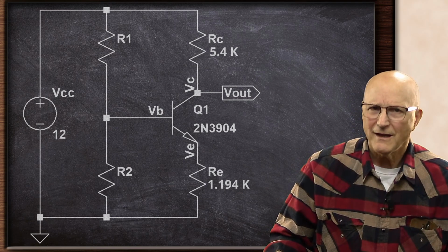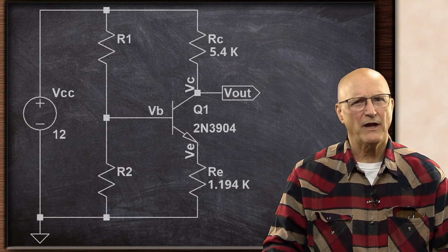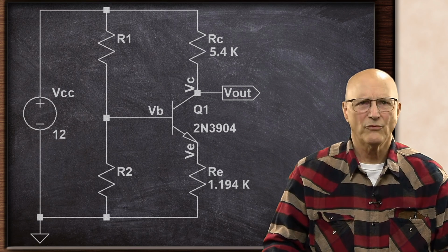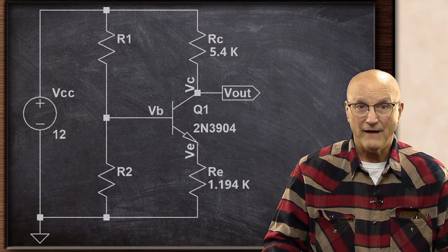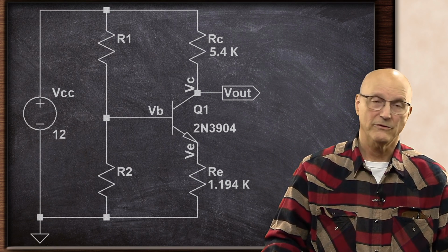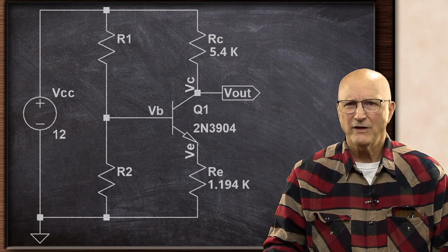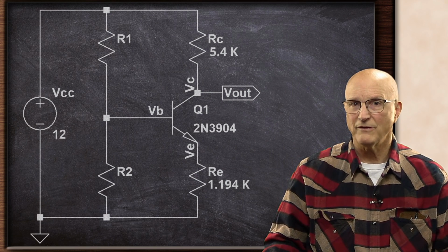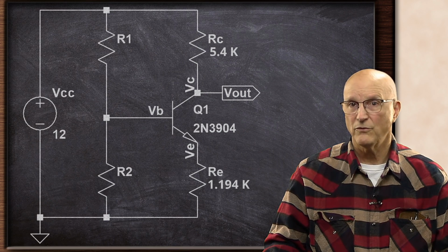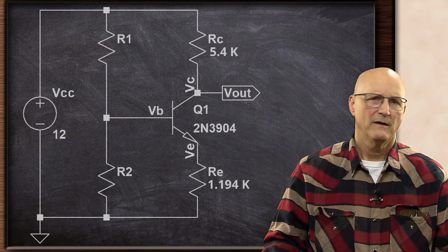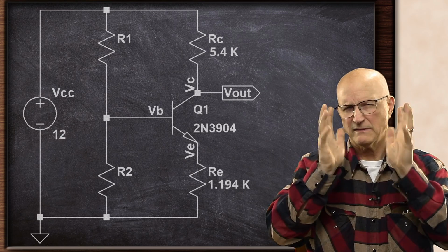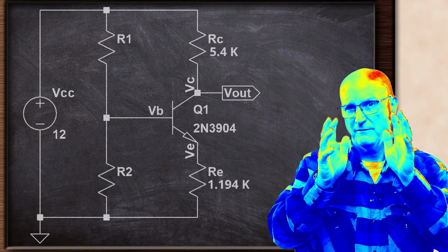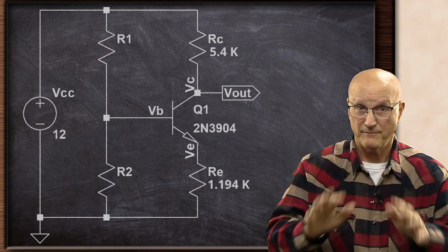While you could leverage Kirchhoff's current and voltage laws with another rule of thumb to find the values of R1 and R2, the most common way to accomplish this is through the use of a Thevenin equivalent for R1 and R2 with the power supply. Admittedly, the whole process is a little weird, but it works.